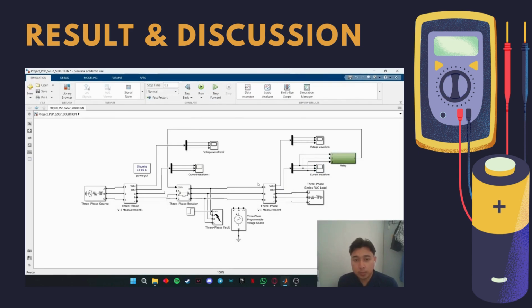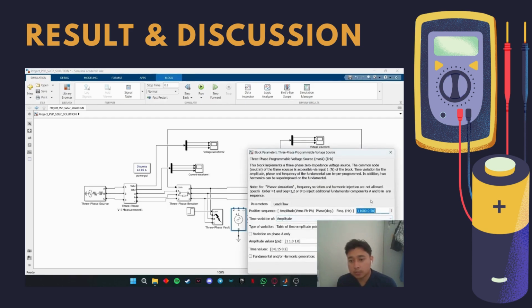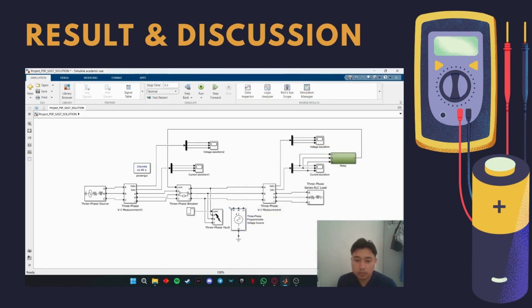So to get the normal conditions, or the good waveform, we suggest putting a three-phase programmable voltage source for each phase. And for the setup, we put 11 kV on the amplitude and 50 Hz on the frequency. And then we need to do this for each phase. And then we need to run the simulation to see the result.